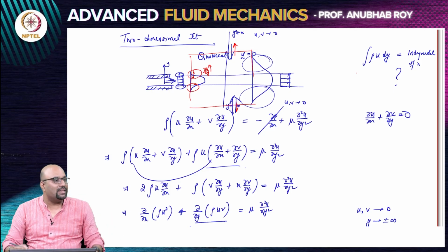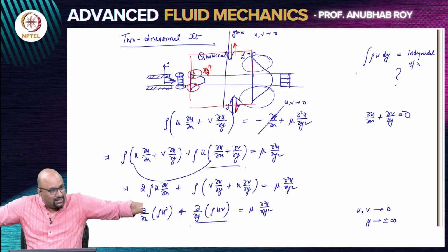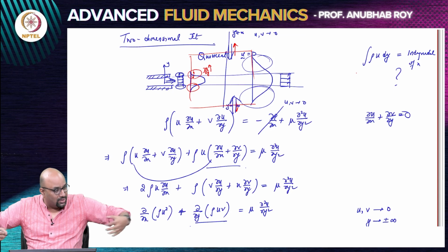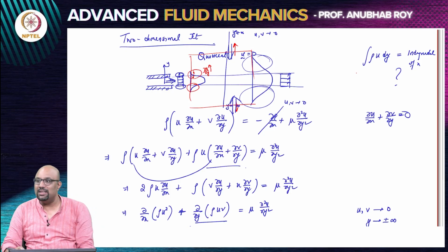There is an entrainment that is happening. I spoke about this idea of entrainment. There is a jet that enters into a fluid. The jet is drawing in fluid from the side. So it is bringing in fluid from the side, which means that the amount of stuff that I am going to carry out will not be the same that I have brought in, because otherwise it will violate mass conservation.